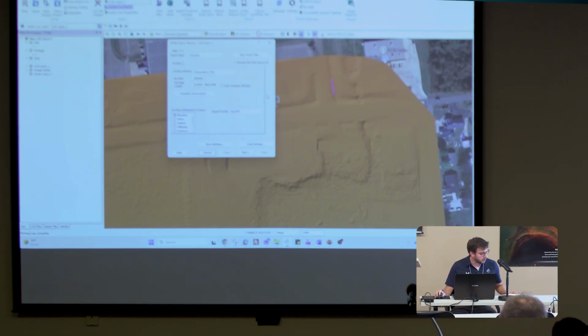As you see, cell edge length, let's make that pretty small. Let's actually go even a little bit smaller than what I list in step 2 on page 47. Let's do 20 centimeters instead of, I think I had you in the exercises set to a third of a meter. The data set's in meters here.